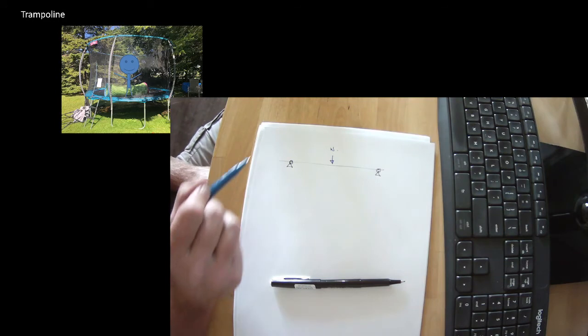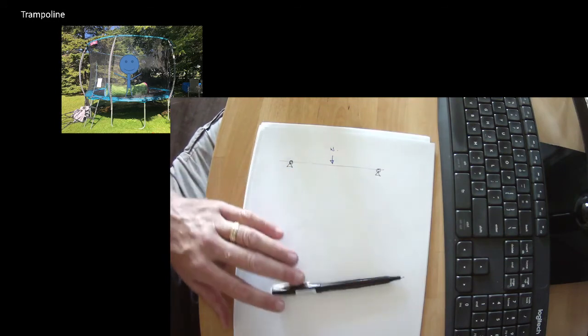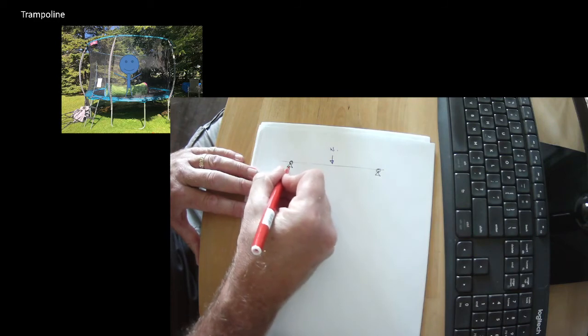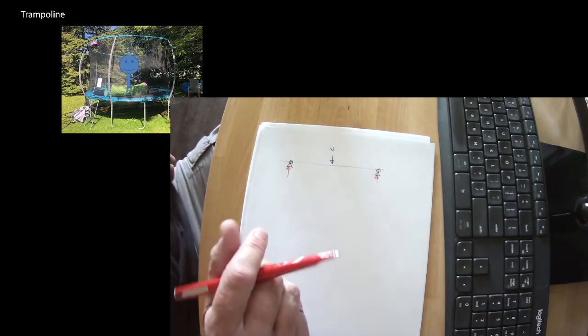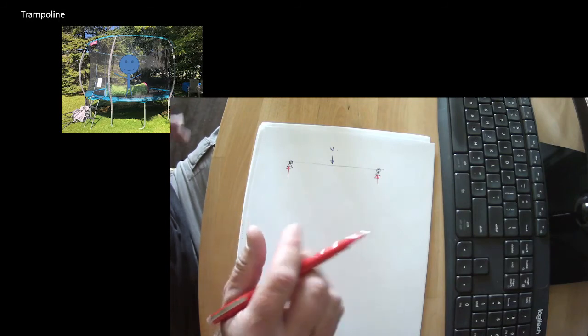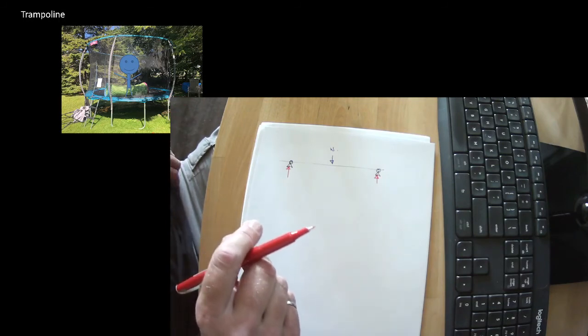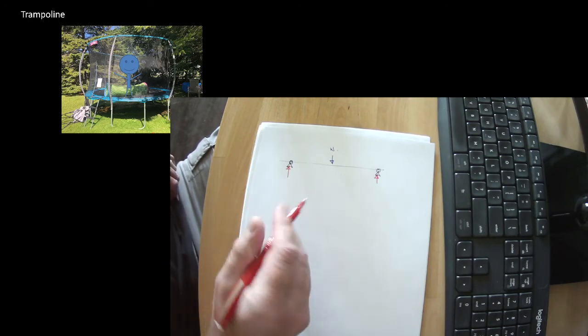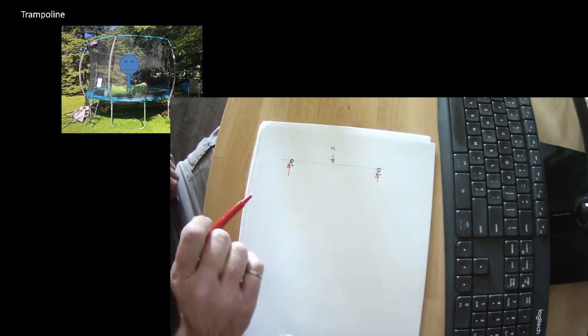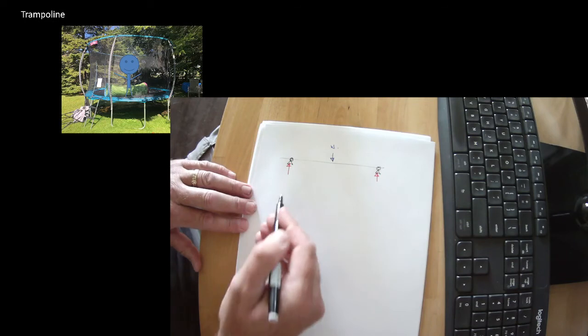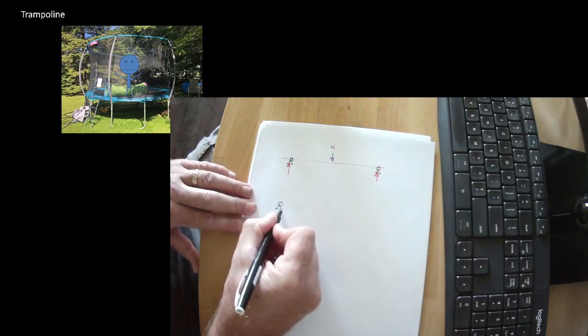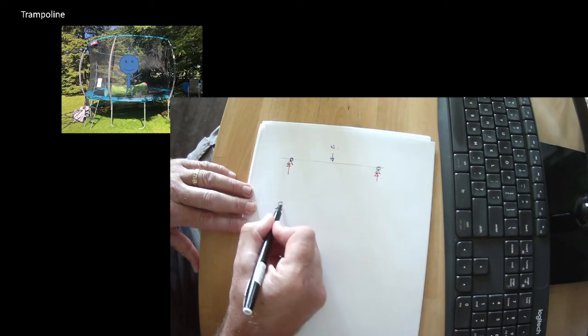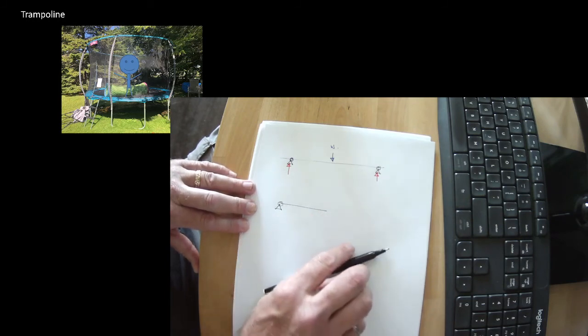And we have weight. Now, I have been drawing external free body diagrams. If you draw this, you're not wrong. But Shannon talked about method of sections before, and the basis for it is that if an element is in equilibrium, then every part of it must also be necessarily in equilibrium, which means you can cut it anywhere and it has to be in equilibrium. Let's cut our trampoline and say we're only going to look at this side.